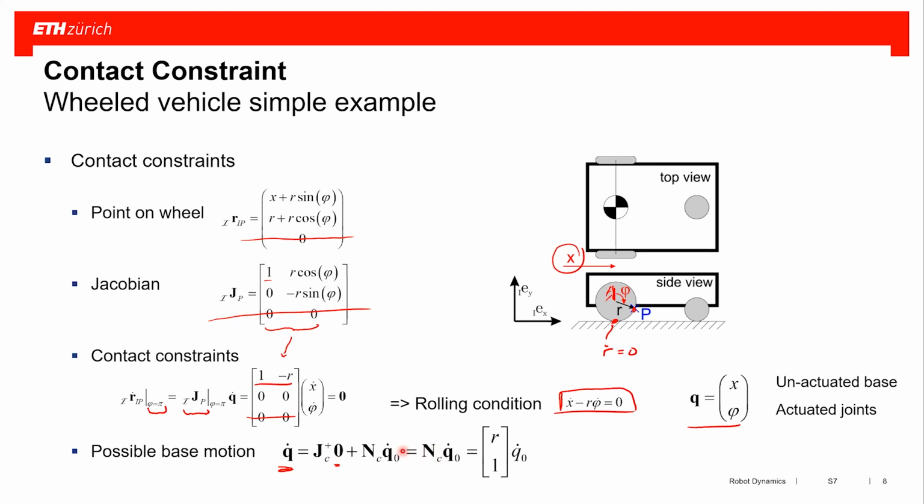And now we have derived one possible null space with Jacobi transposed inversion, so the pseudo inversion of it, and then identity minus this part. This is a way we can do it, but this is not the way I would typically suggest you do it. If I look at this matrix here, I can actually directly spot a potential null space projector.